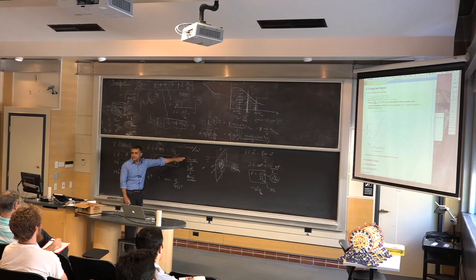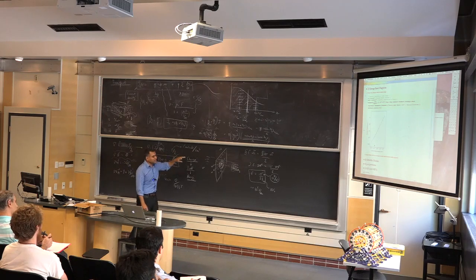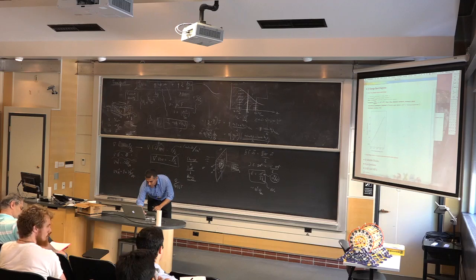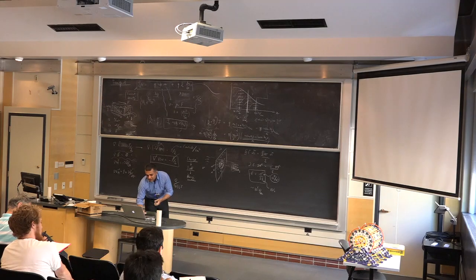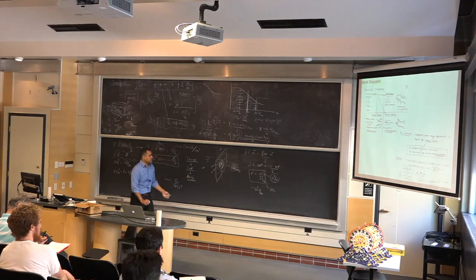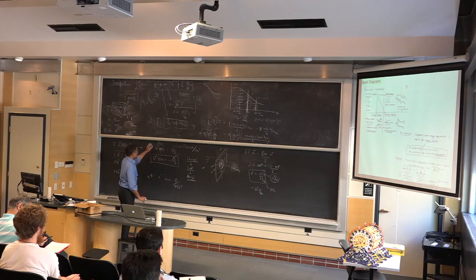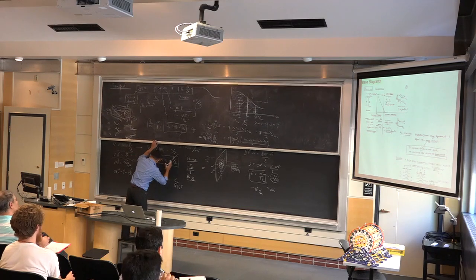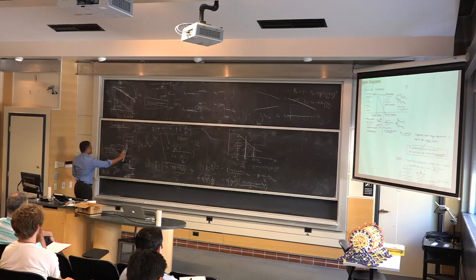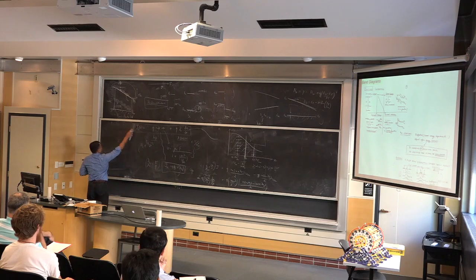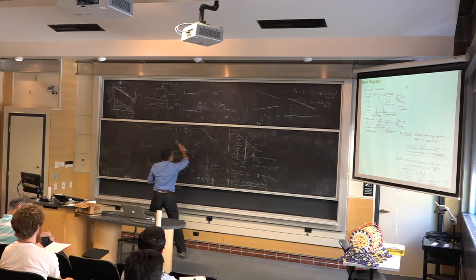Is that clear? So as a result, if I have this sort of a field, and you told me I have a charge and you gave me the field, how should the energy band diagram look like? Let's try to draw it. So the question now is, I have a sheet charge that I have inserted into a piece of semiconductor. And then ask, draw me the energy band diagram around it, nearby it and all that.